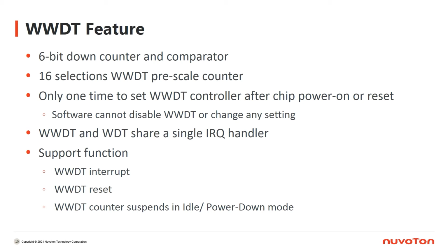WWDT and WDT share the same interrupt handler function. Like WDT, WWDT can trigger an interrupt or a reset. However, unlike WDT, the counter of WWDT can only work in normal run mode. It will suspend in other modes.